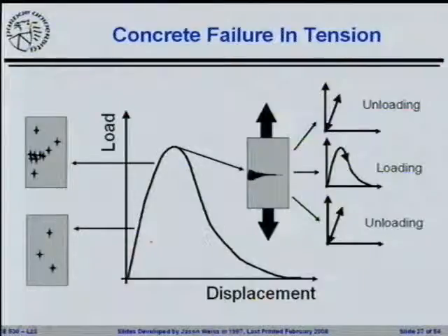One second, Javier. In the pre-peak region, you have microcracking. You get up to the peak region, and all of a sudden, you've got the bulk material that's loading and unloading in an elastic fashion, and you've got a localized region where the crack is going to be growing, softening, and transmitting stress across that softened crack.